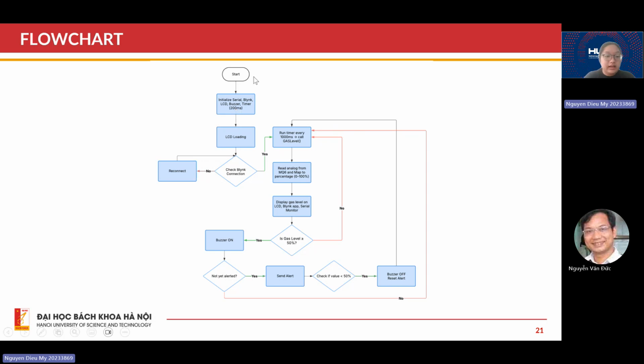The process begins with initializing all the necessary components, including serial, Blink, LCD, buzzer, and the timer every 1 second. After a short system loading display on the LCD, we check for the Blink connection. If it is not connected, the system will attempt to reconnect automatically. And once connected,